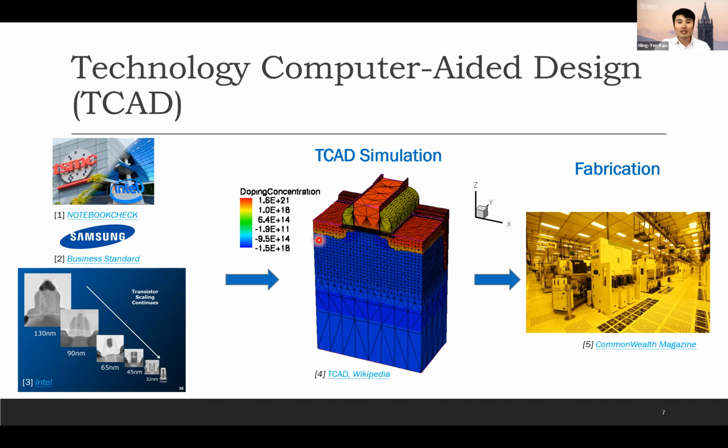The first one is the geometry: the transistor designer has to build the geometry virtually in the computer. And second, they choose which physics equations they would like to include, and the TCAD simulator will solve those physics equations self-consistently within these grids, and give out the target transistor characteristics. If the simulated transistor characteristics comply with their expectations, then they can put in a trial run in fabrication.